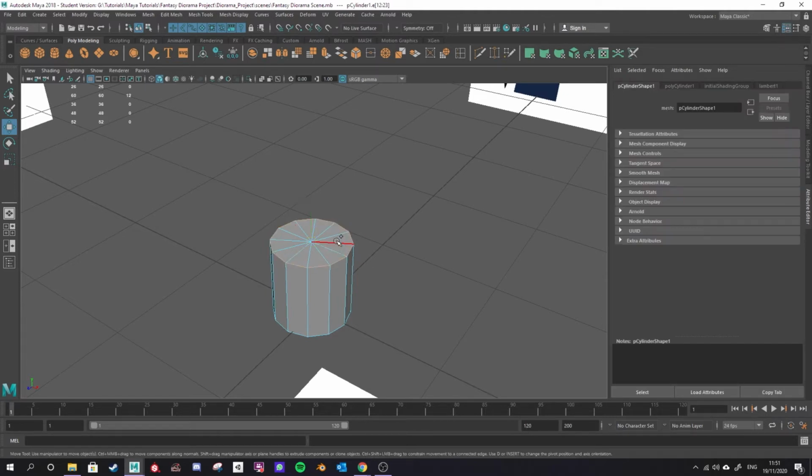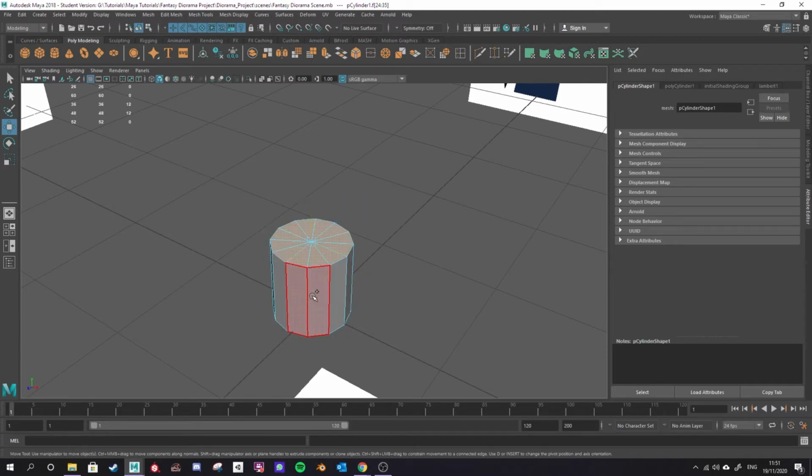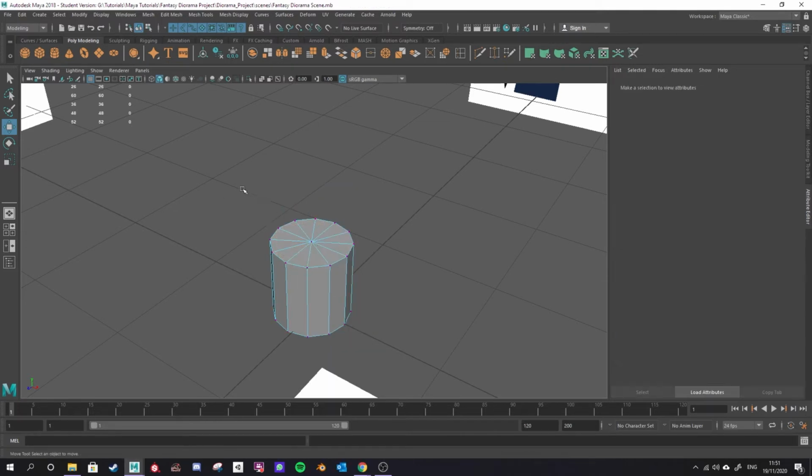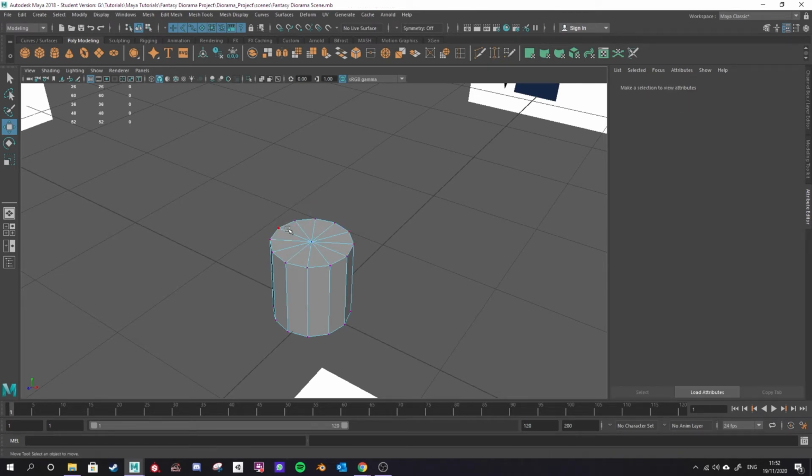And if I accidentally make a selection, like I accidentally select some of these edges, I can undo that by holding Tab, and then the minus icon will show up on currently selected edges, and then let go. Same thing works for faces. I can use Tab to select, and I can hold Tab to deselect. If you're not holding Tab, Shift will be the modifier to deselect individual edges. Same thing works for vertices. If I have vertices selected, holding Shift, I can deselect certain vertices. And also Tab can paint select vertices.